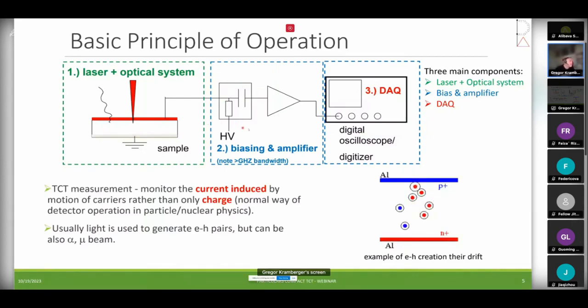The next thing is how you connect your electrodes to the electronics. Remember, we want to look at the currents, and the currents are of nanosecond order. So you really need to have high bandwidth components, and it's not as simple as a resistor and a capacitor, as you can imagine. But this is basically what it is.